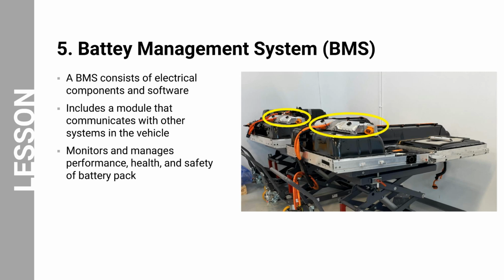Manufacturers may also integrate it in multiple locations so that if one BMS fails, the other BMSs can still function and keep the battery pack safe. The primary functions of the BMS for an EV battery are safety, performance optimizations, health monitoring and diagnostics, and communication.